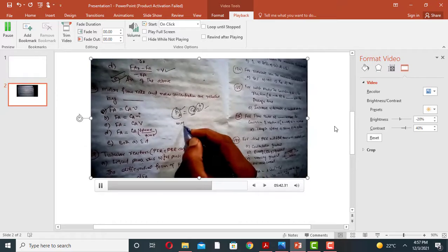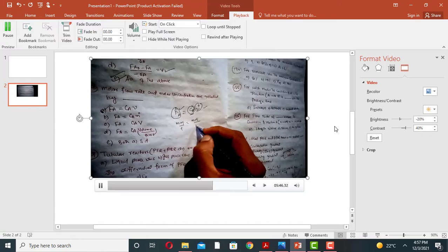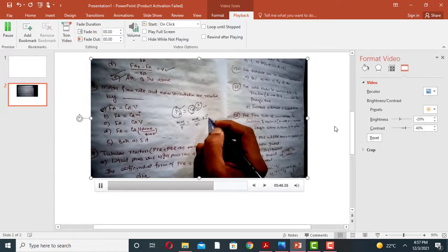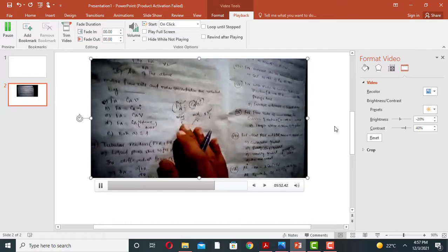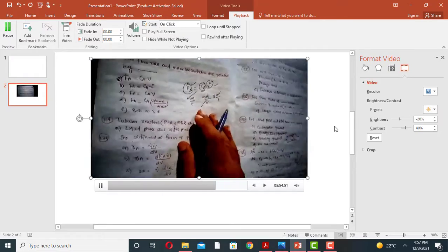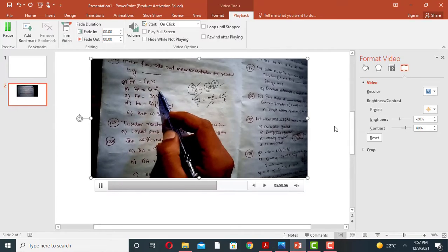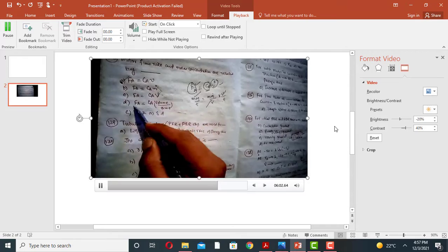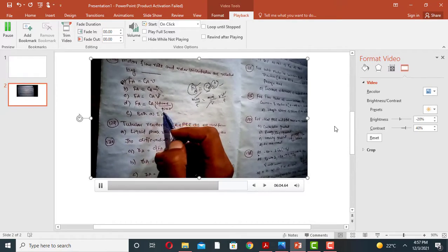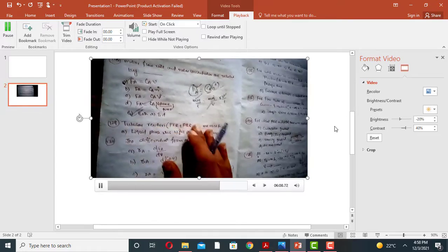FA means moles per unit time, concentration means moles per unit volume, and volumetric flow rate means volume per unit time, so the volume cancels. Moles per unit time is equal to CA times the volumetric flow rate. So both A and D are the correct options.